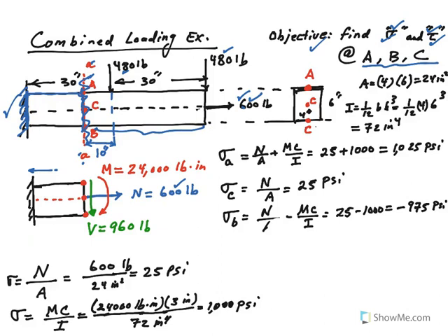Remember when we were doing internal forces, we had normal force, shear force, and bending moment. That's why I'm using N here. The two 480 loads, when transferred to this section, become 480 plus 480, that's 960, and that's your shear load. So you put that right here.